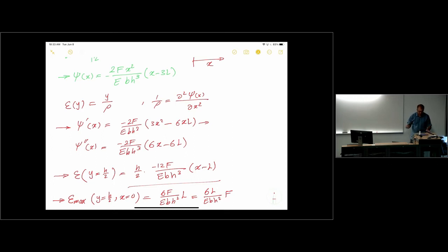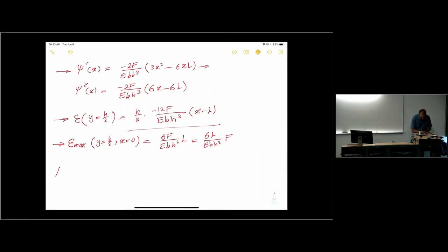And we have a piezoresistor there, so what you can say is that delta R is the gauge factor times, so remember gauge factor, let me just go back to the definition here. Remember gauge factor was defined as delta R over R normalized by strain, or the sensitivity of delta R over R to strain.